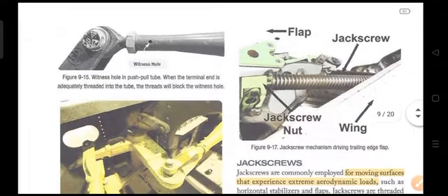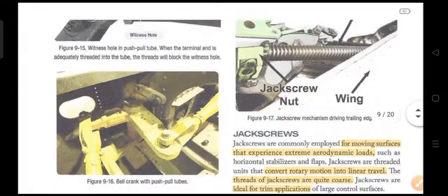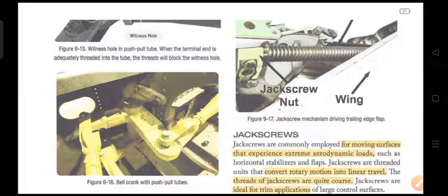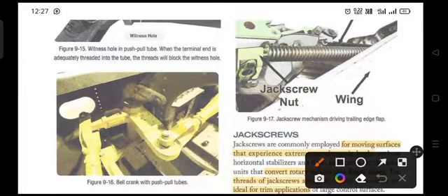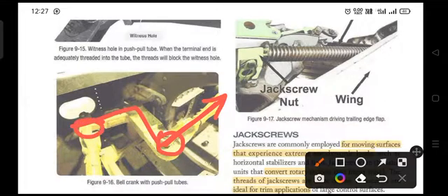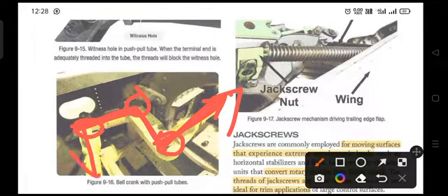So these are the pictures that will give you a brief idea about what is happening. See, this is a bell crank. A bell crank is a thing which is used to change the direction, or rather any offset direction. Like this side it will be pulled, so over here there is a hinge mechanism, there is another hinge mechanism over here, and there is a third hinge mechanism in the middle. So basically this is the bell crank, actually only this much. And when this is pulled by a push pull rod on this side, then this end will go this side and this end will be pushed in this way.